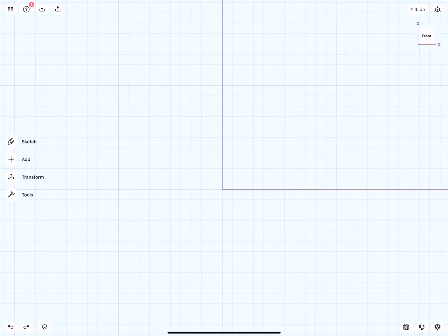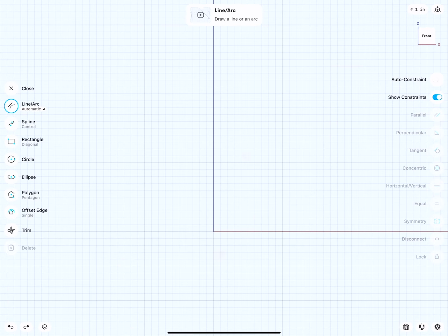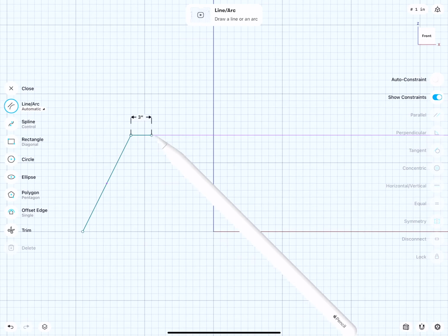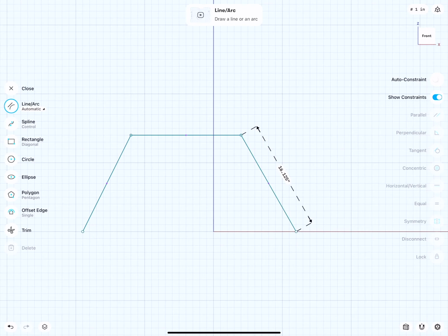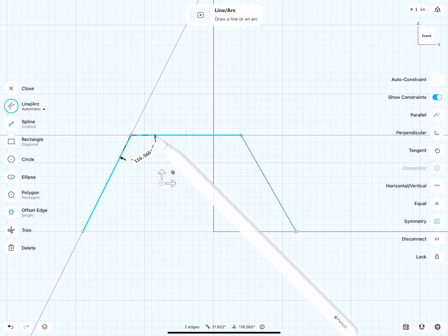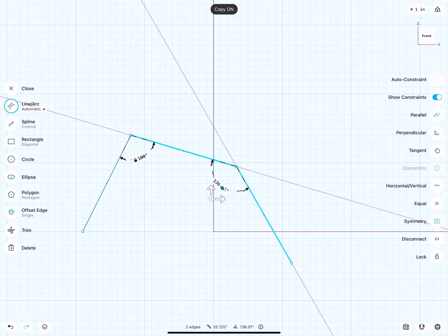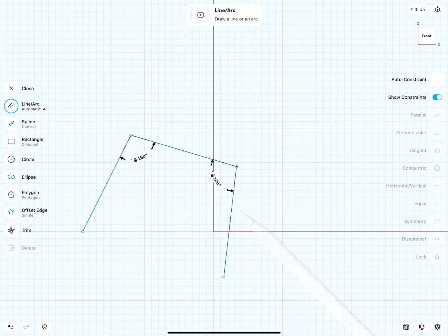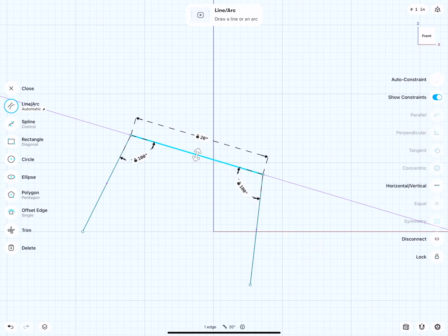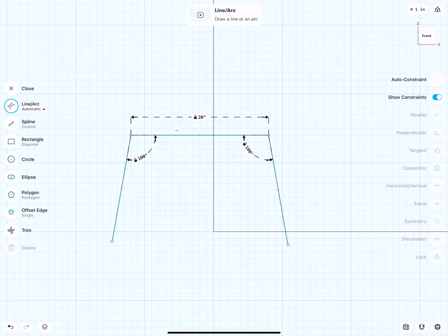As you see, I went to the front view and we can start with our first sketch. I will draw a side line, a horizontal line, and another side line. The degree between the side and the horizontal should be around 100. Same here. And you can see that everything rotated a little bit, not a big problem. This line should actually be around 20 inches, and when I select it again, it should be straight horizontal. It's on the right side. Let's select horizontal vertical. There we are.